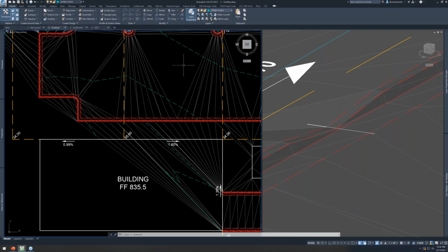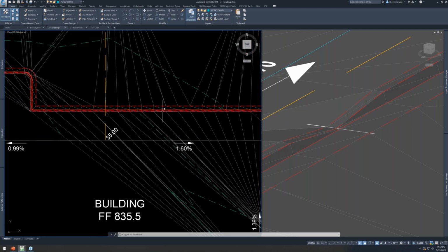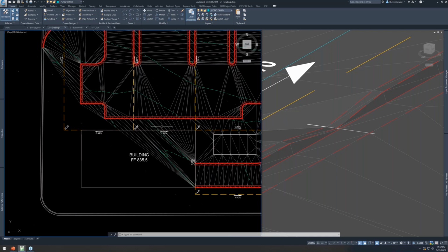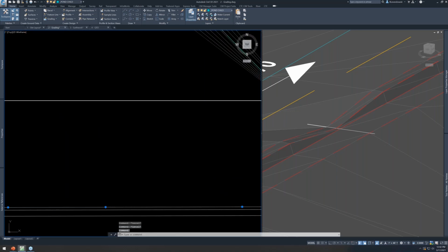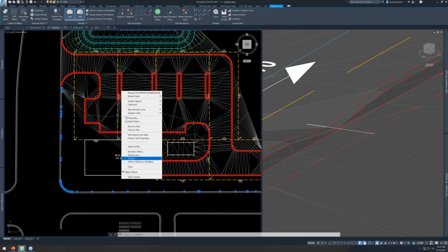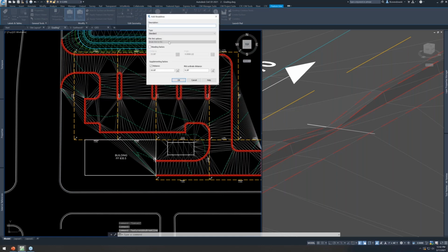That same curb cut thing we did over here, you do the same kind of thing up here for pedestrian ramps. All works the same way. Obviously, you probably use 2 feature lines there. I like to pull in my existing feature lines. If we want to add this into the surface, this is where we're tying in to the existing back of curb, so we can call that X curb.